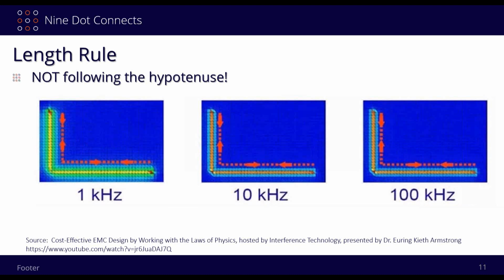So in high-speed design, therefore, we have to remember, A, we're dealing with a closed loop, and B, we better have some type of material underneath this, something that it can conduct itself and travel back on. Otherwise, it's going to try to find its way back to point A. The question is, are you going to give it an easy path to go by, or is it going to be banging around and creating a tremendous amount of noise in order to get back to point A? Regardless, it's going to get back to point A. So we've got to be able to control that. And that's why it's really, really important that we understand the length of these things and that we do have this closed loop over here.